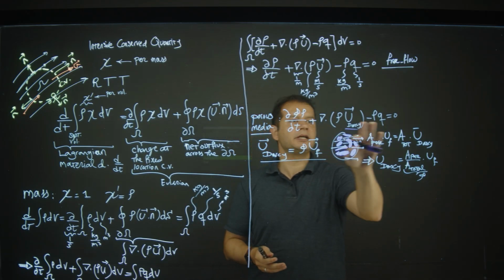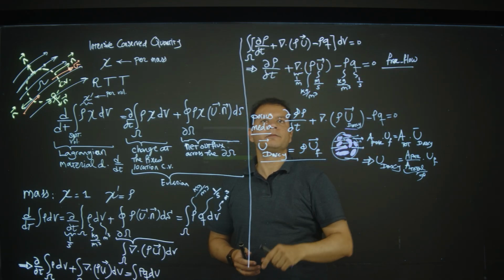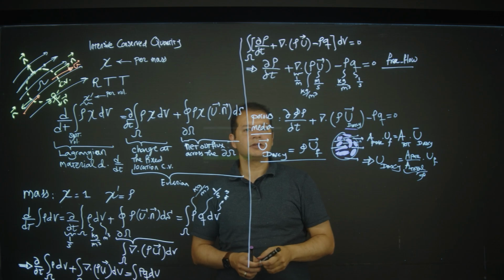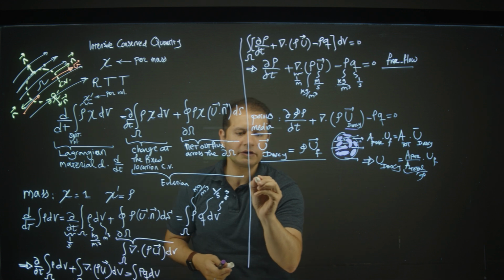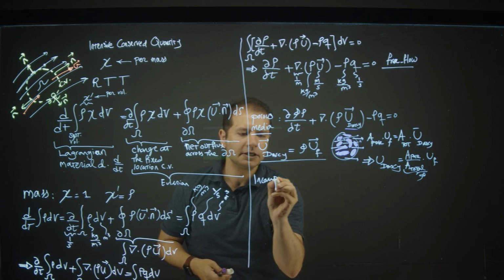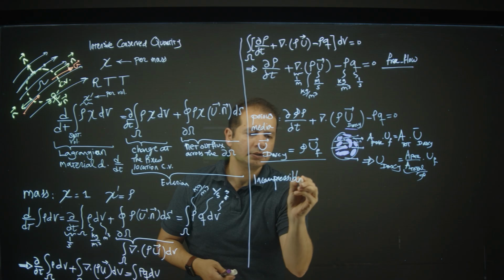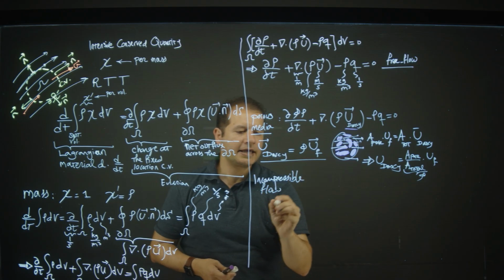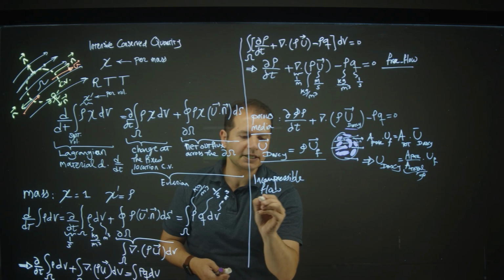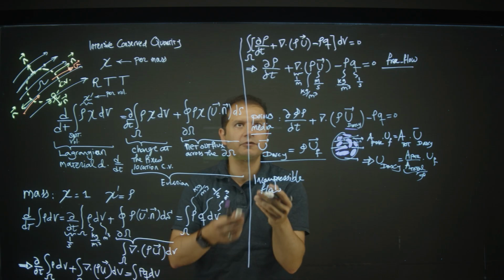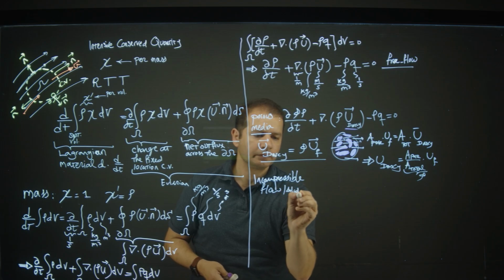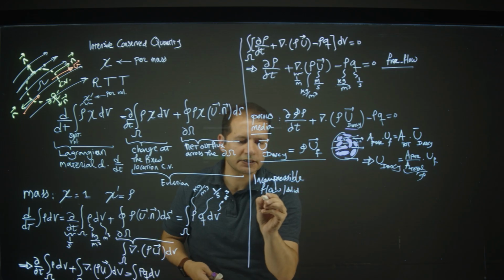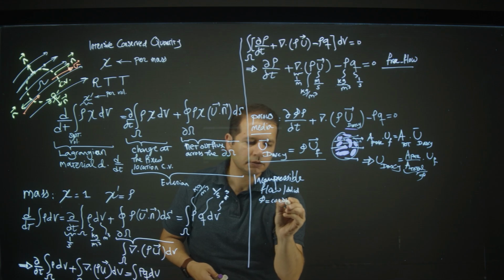So that's for porous media, and that is for free flow. Now remember one thing we did. Either one, porous media or free flow, doesn't matter. If you're solving for incompressible flow, and then assume that also porosity is constant if you are doing it for porous media, so then incompressible flow and also incompressible system, flow and solid, or porous media, so porosity is constant and density is constant.